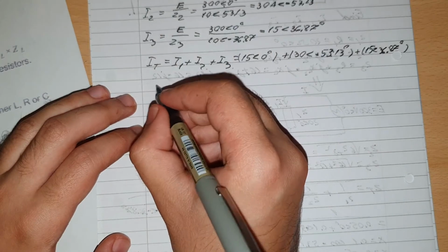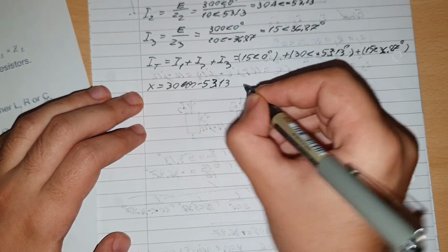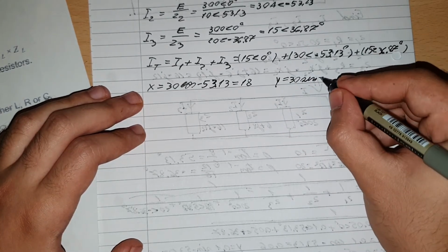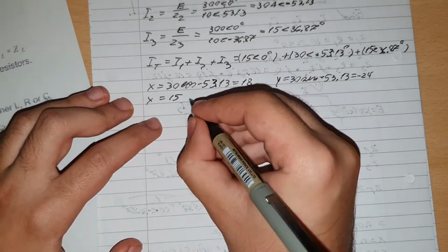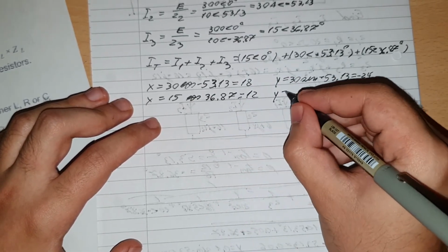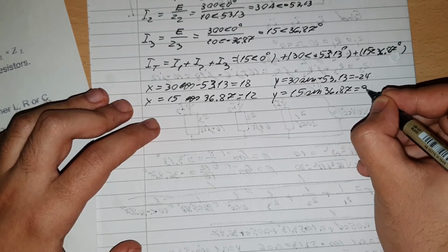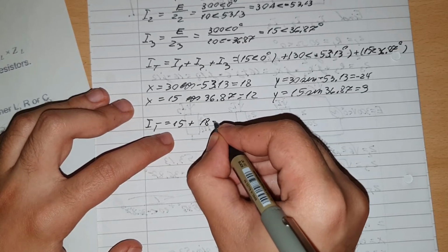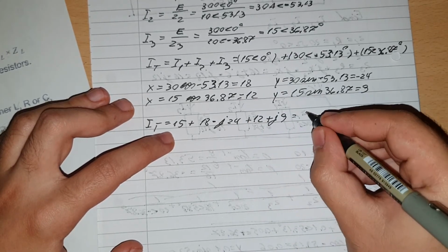Okay, so then the x value will be equal to 30 cos minus 53.13. I start running out of ink, I think. That's 18. Y is equal to 30 sine minus 53.13. That's equal to minus 24. X is equal to 15 cos 36.87. That's equal with 12. And y is equal with 15 sine 36.87, and that's equal with 9. So IT would be equal with 15 plus 18 minus j24 plus 12 plus j9, and that's equal with 45